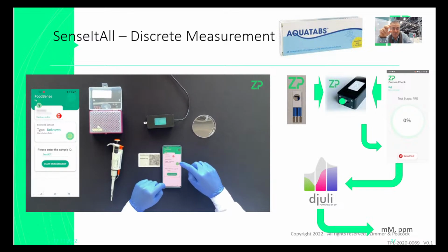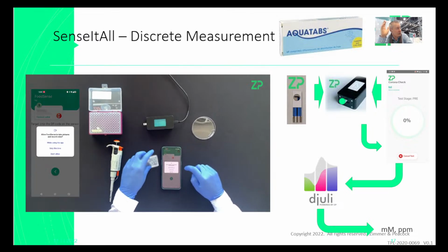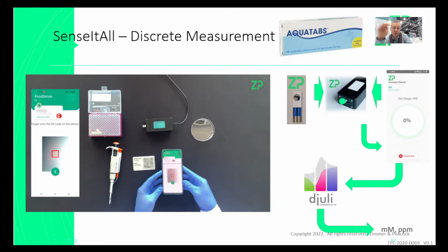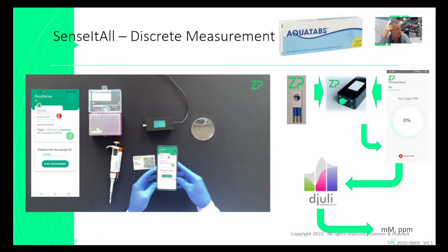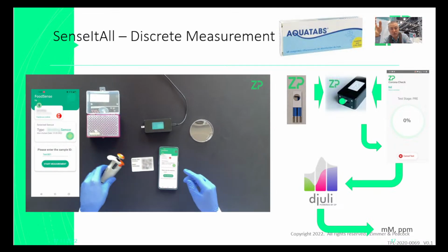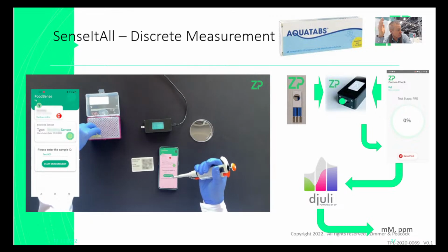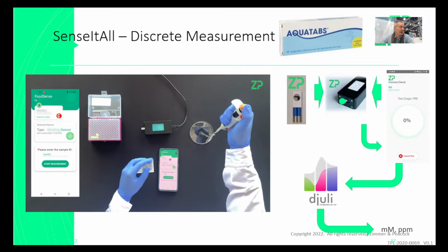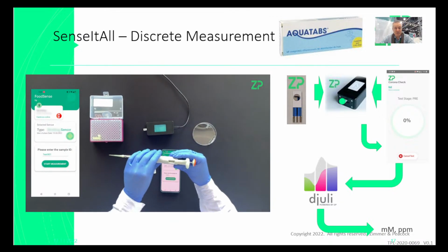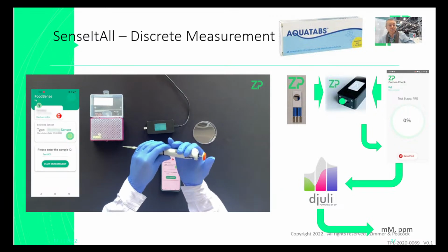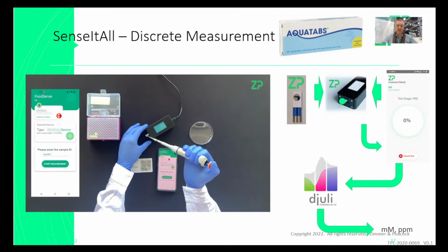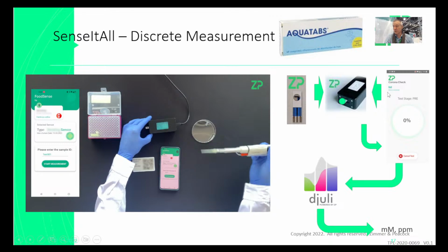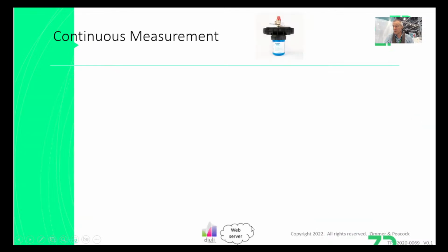And then they could check that the free chlorine concentration was actually high enough. If it was too low, it tells you that you had quite a lot of contamination in there, that all the chlorine is consumed, and so you have no certainty that that water is fully sterilized. So this is a good way of testing. If after, let's say, 20 minutes there's no chlorine left, it tells you that you've probably still got material in there that needs sterilizing, and you might need extra tablets. So this is what I call a useful spot test to make sure things were working okay.